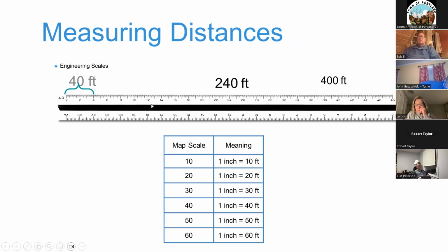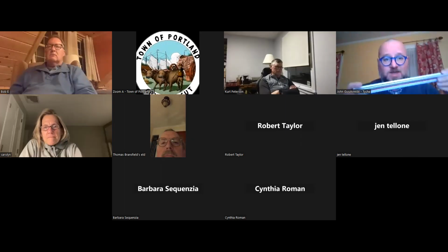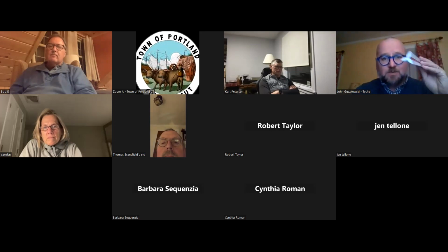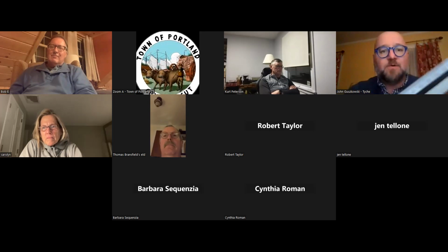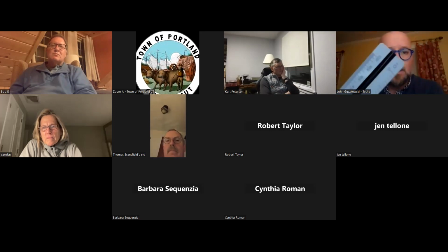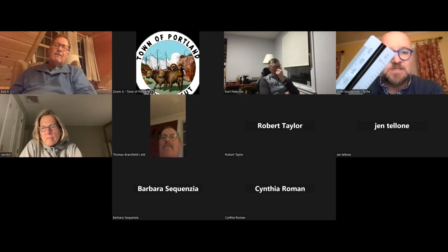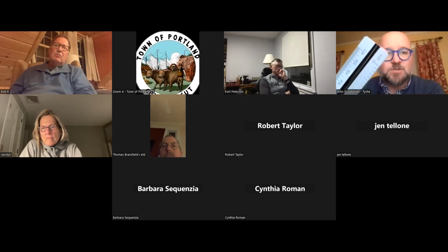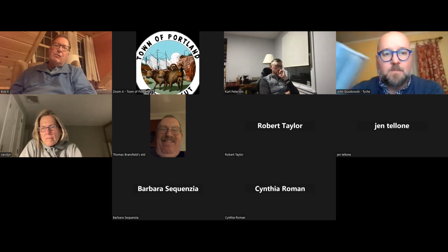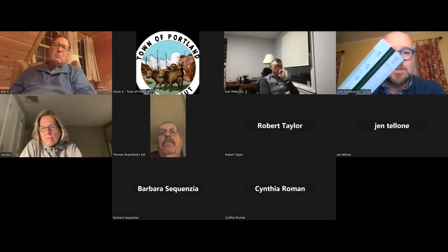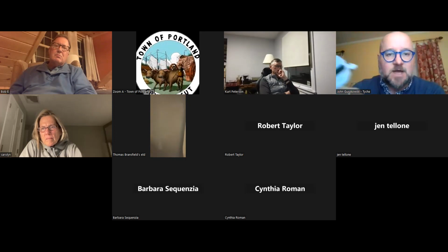I had one here in my bag. I'll stop sharing my screen for a second, so I can just illustrate this. I'm sure that you guys have seen these triangular scales. Up in the corner, you can see the 10. So this basically has 6 edges. It's got a 10 scale, so 1 inch equals 10 feet. It's got a double edge there, that's 20 scale. On the opposite side, you see the 40 scale.